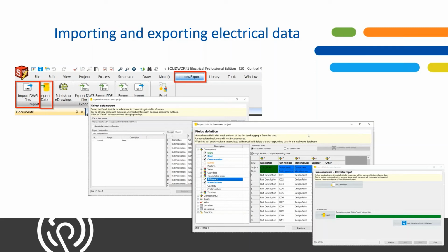Once you finish that 3D routing, or even flattening a cable in 3D, you could take that information, even your bill of material as well, from your 3D flatten layout or from your route. And then you can export that, and then you can import that back into 2D.